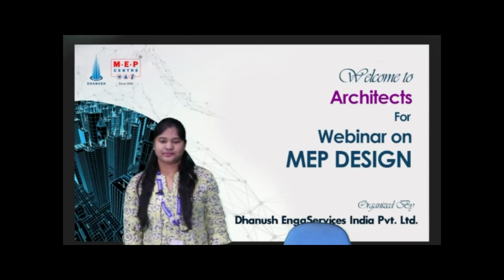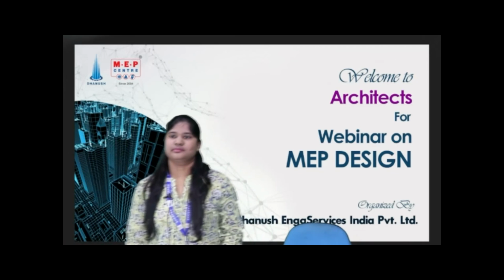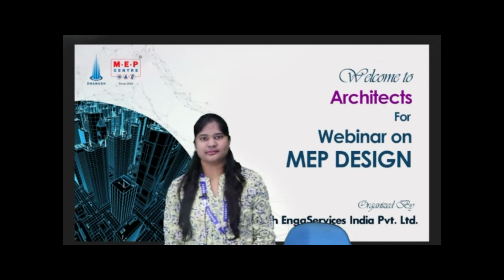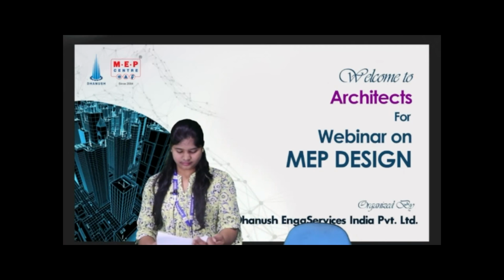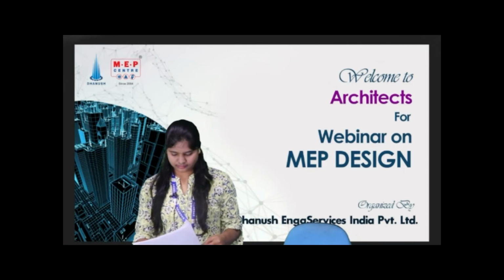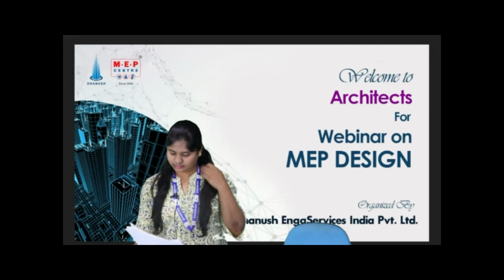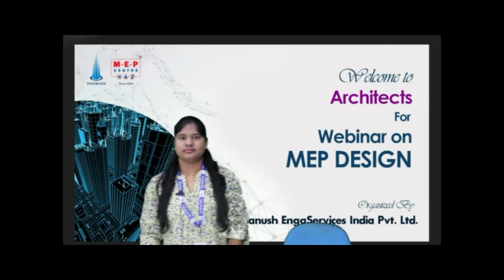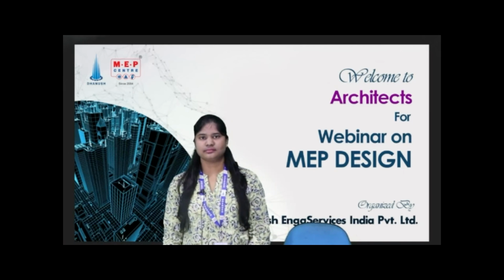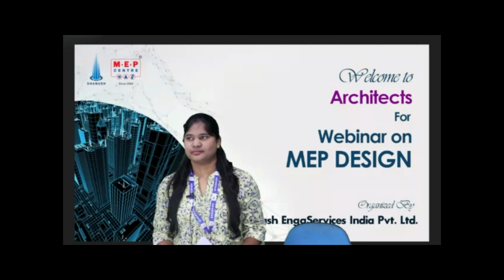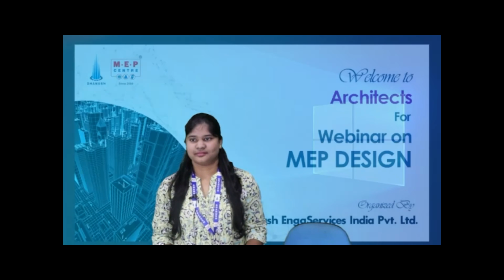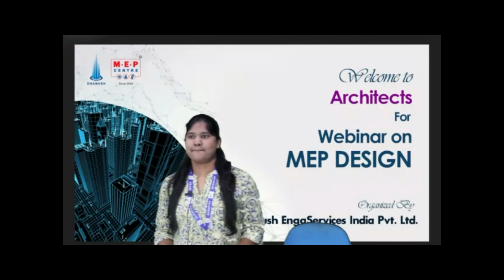Good afternoon, sir. Good afternoon. Sir, can you provide openable windows in the fire staircase, or do we have to open it manually? No, these are motorized openable windows, integrated with the fire alarm system. Whenever there is a fire, the fan will be actuated, and at the same time these motorized openable windows will also be actuated so that they open automatically, like an AOV, automatic operated ventilator.